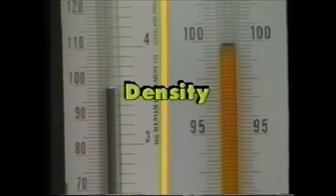Remember, we said that hydrostatic head varied with the mass or density of the liquid as well as its height. The reason these two manometers don't have the same level is that they're using two different liquids, water and mercury. Since mercury is heavier than water, it doesn't rise as high as water when the same pressure is being measured. The term used to compare the mass of liquids is density.